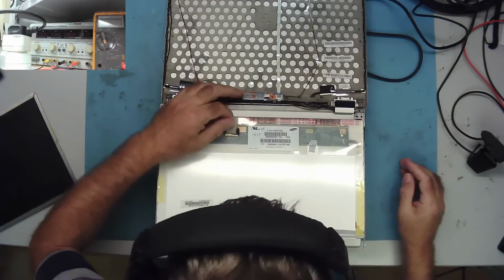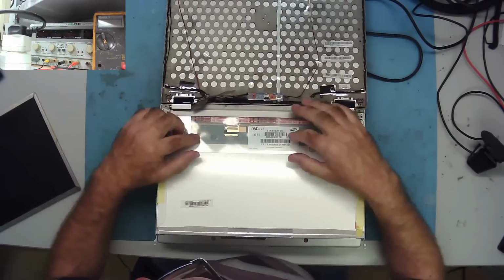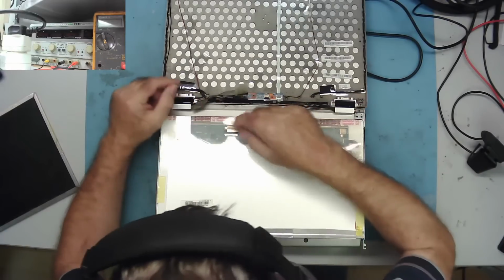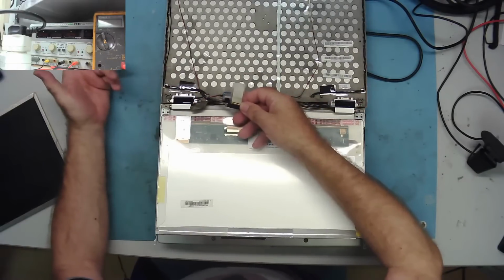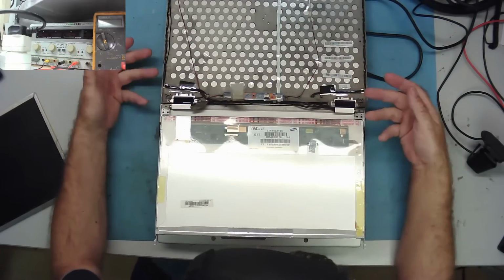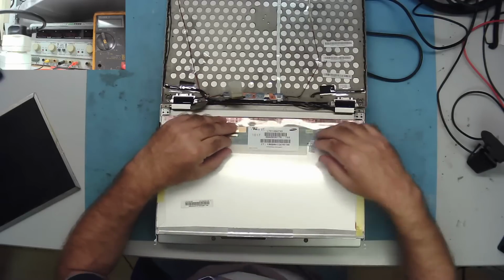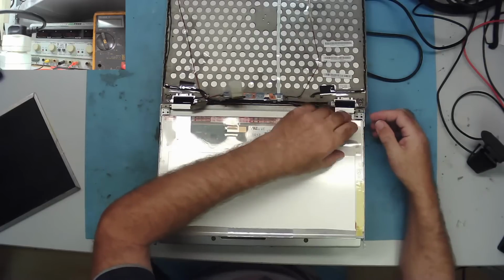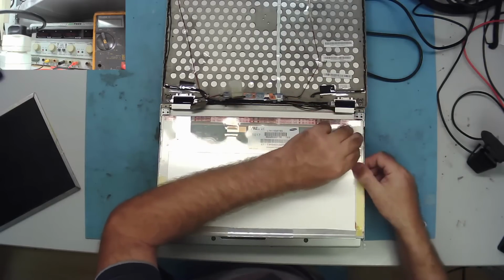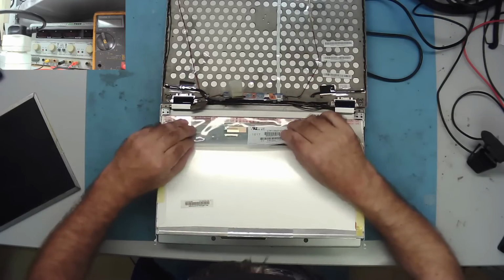Well, let's power it off. I'm guessing we need to have a look under here. Because we know the video's coming in working because the screen gives a picture, so we know that that's okay. So the problem's here somewhere. The backlight works, that's fair enough, that's coming in here. So something I suspect is wrong on this circuit board. I don't think it's the screen panel itself. I mean, normally if a screen panel fails, it's giving lines on the screen. It could be. I don't know.